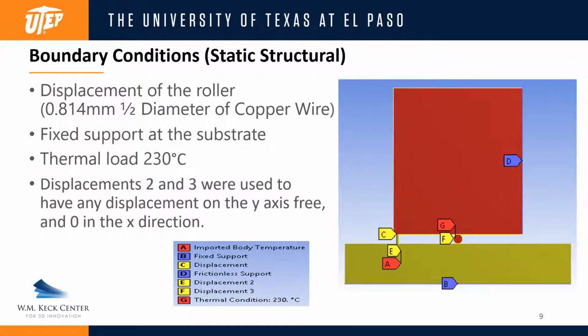Then after doing the steady state thermal analysis, I went ahead and added the static structural analysis, which is going to help me determine the deformation of the substrate. So right on A, it says imported body temperature, which is going to be taken from the previous study.